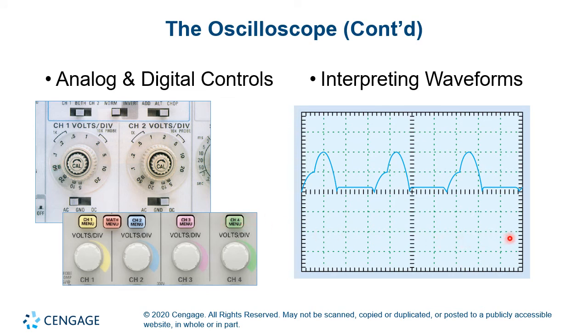What we use an oscilloscope for is to look at the waveform. Things like how often does it repeat? Does it go positive then negative, or remain positive? For example, this would be referred to as a DC waveform, although it's changing. It's always above 0, so it's always positive.